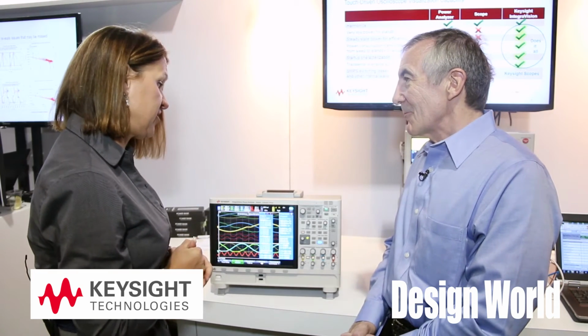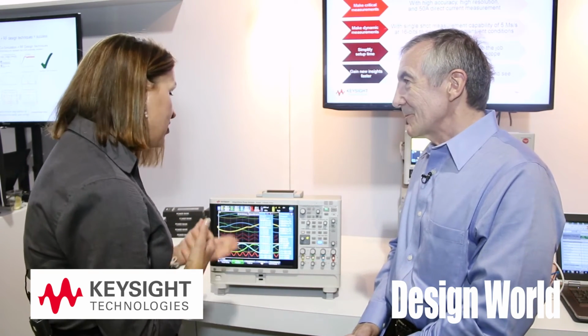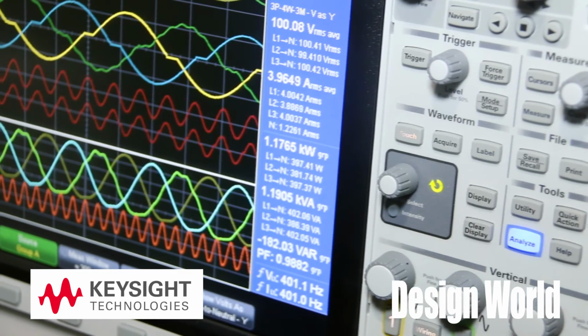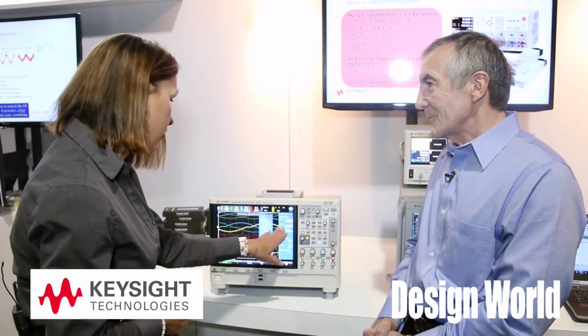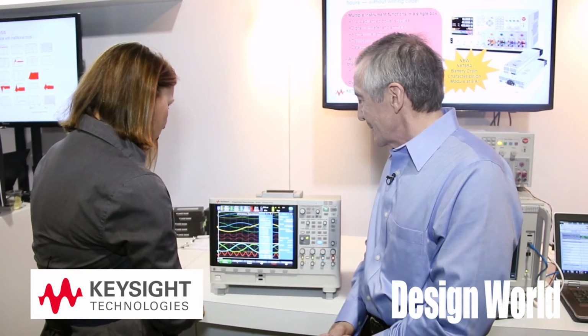The basic accuracy of this tester is 0.05%, but with this new technology, we deliver the RMS and the power quality measurements with very high accuracy, because we make sure that we don't lose any data. So those are your power quality measurements. Now, the next thing is interesting. For example, you want to know the efficiency when your design is operating. It's very quick, again, you push 2 buttons. There is your efficiency, around 73% from one side to the other side.